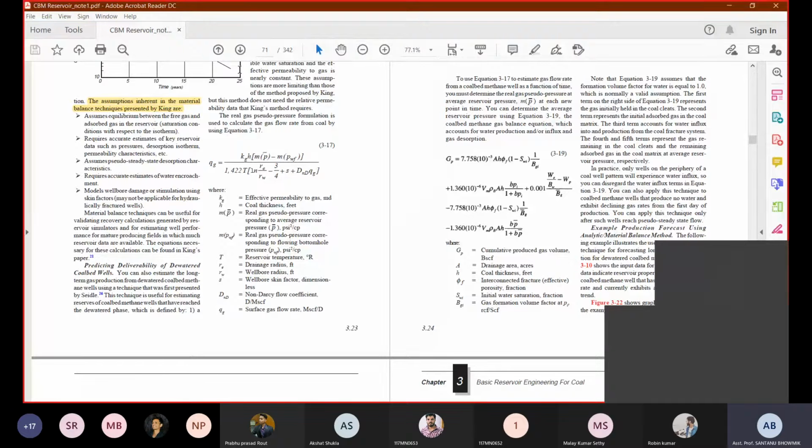Or maybe that water with very high head, very high pore pressure, can create fractures in the rock. Okay, so you have also studied some part of soil mechanics. So you must have understood two important terms, the drained shear strength and the undrained shear strength. You know about the drained shear strength and the undrained shear strength?